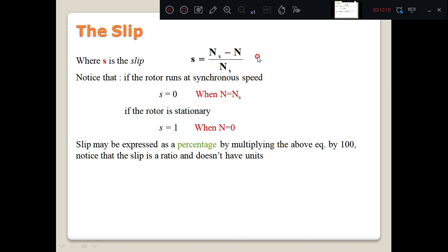It is one of the figures of merit of an induction motor that the slip is as minimum as possible, so that the difference between ns and n is less. Whenever the induction motor is loaded, the drop in speed is less, so the slip is well within the limit. Usually for standard machines, the slip of the induction motor is less than 3%.